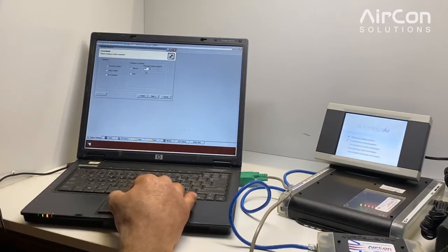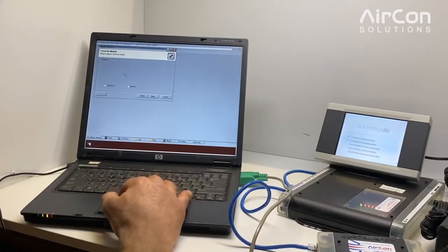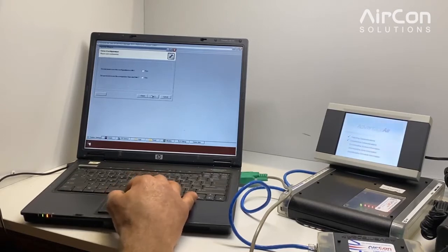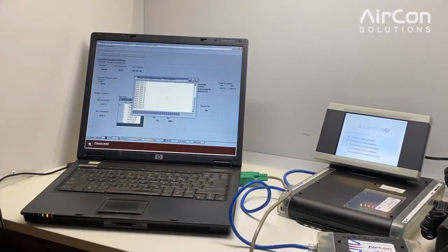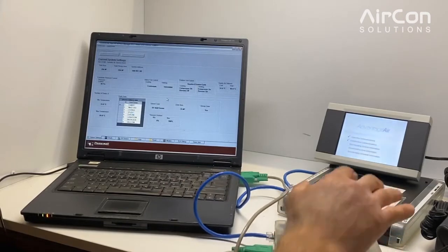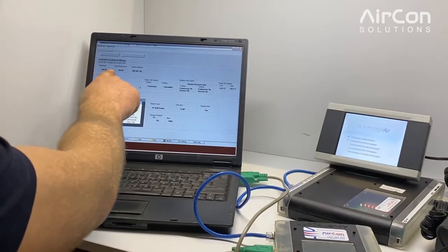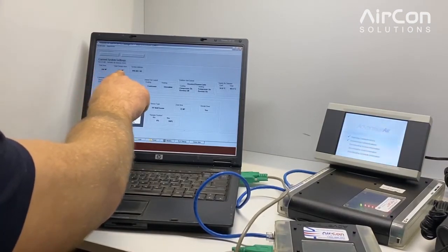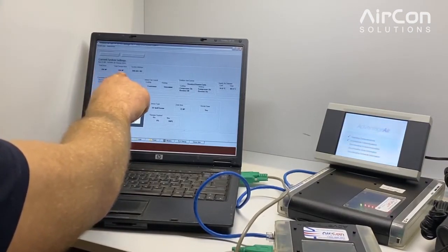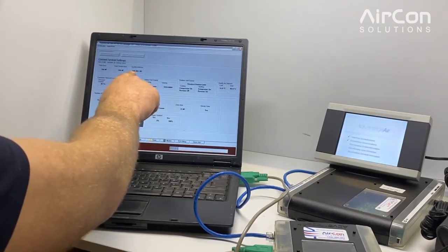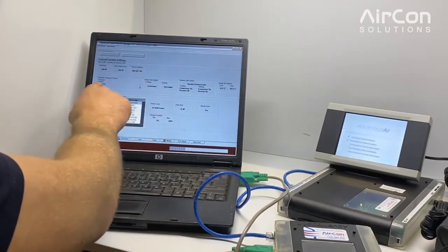So we set up pressure, set for 30. The customer's got a PA of 30 on their system. You can have options for fresh air, which you can source from outside or from in the roof. None of that applies for this job. And we're transferring the data through the dongle across to the main board. You can see now, total area is 204 square meters. All zones are design zones according to the information given. The system address is there.